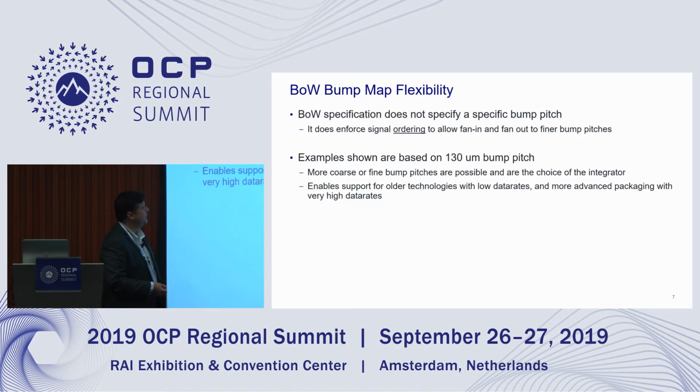So we don't enforce any specific bump pitch in the proposal, but we are enforcing a signal ordering to address a challenge I think that Wolfgang's going to share with us at the end of the day, which is if you've got multiple bump pitches for multiple die, how do you make them actually integrate together?